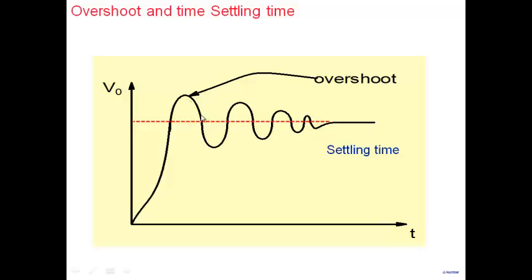The other thing is, how long does it take to settle down to its final value? So, settling time. Starting from this point onwards, where it rises to its maximum, how long does it take to settle down to within a few percent of its final value? So settling time is important as well when we look at the time response.